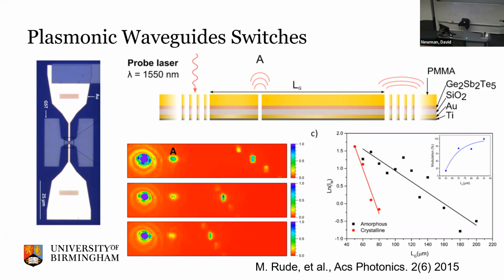The idea of this was to make some kind of plasmonic RAM, some sort of electrical memory that you could read plasmonically. So this is the reason this GST is shaped in this way. You could pass a current through it, heat it up, crystallize it, and measure the surface plasmon polariton waves through it. So that was the whole idea behind this paper.